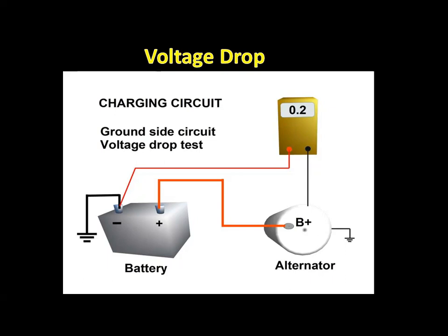When a set of switch contacts becomes pitted and corroded, they may have a 2-volt drop, which reduces current flow in the circuit. This voltage loss is caused by the high resistance and the corrosion. The high resistance allows the contacts to act like another load in the circuit, the same as if you added additional components to a circuit to the point it ceases to function correctly.